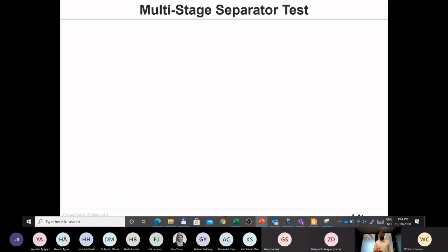Then you have uncertainty about how much you have removed, and whether you measured the removal accurately. In this experiment, it's very simple. There is no removal. If it's done accurately in the PVT lab, it's a very good experiment to tune the PVT model. But of course, when there is no removal, there is very limited QC of the PVT experiment because you cannot do any kind of material balance.